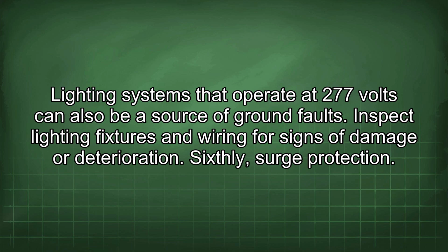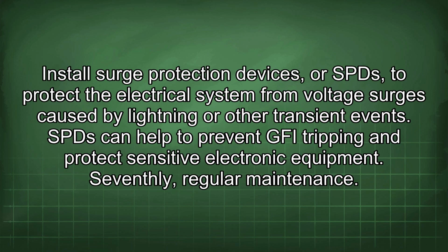Sixthly, surge protection. Install surge protection devices, or SPDs, to protect the electrical system from voltage surges caused by lightning or other transient events. SPDs can help to prevent GFI tripping and protect sensitive electronic equipment.